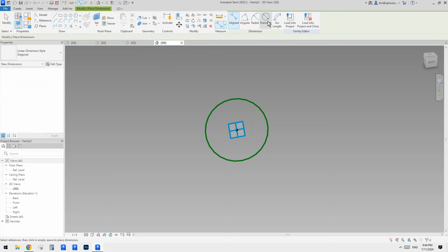yeah, it's here. So I'm going to place it on this midpoint, and then make this point driving, okay, and then make it adaptive. So now we have 1, 2, and 3. And that's it. You can type HR to bring back the sweep. Load this one and overwrite. Now we will have one extra point in the middle.